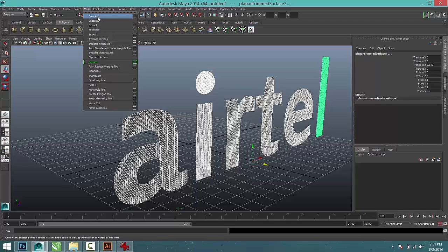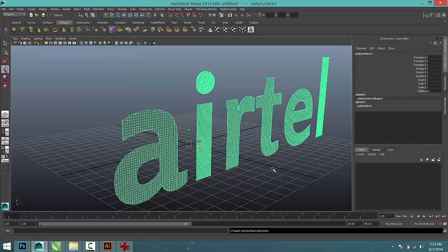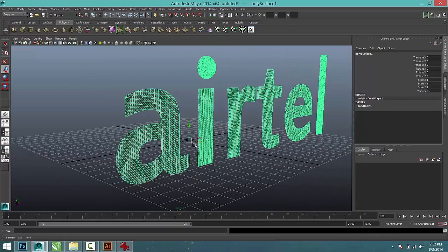Now there may still be spaces within them as this one has, but it will not change the fact that they are all one mesh, because the software will always recognize them as one mesh as opposed to separate meshes. So if I do Combine, you can see that the colors have changed from multiple selections to only having one selection.